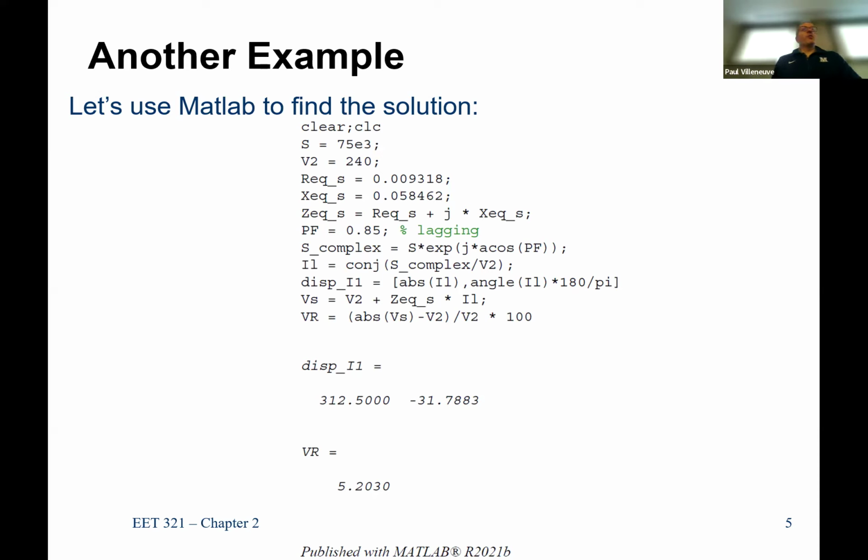And those of you who went to the community college and did any classes with the National Electric Code, there are requirements about not letting the voltage drop on any device exceed 3%. So you have to reconfigure your design if you have really long cable runs to make sure that you're limiting that drop to less than 3%. Usually it's never a problem to go up, or it hardly ever goes up. It almost always goes down. So lower voltages tend to be the issue, not higher voltages.